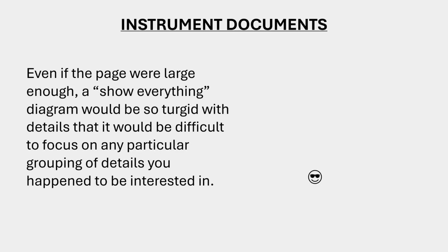To fully understand the control system, technicians often have to switch between these diagrams. You might start with a PFD, the process flow diagram, or a P&ID, the process and instrumentation diagram, to understand the overall process. And then you move to a loop diagram for wiring details, and then you can finally check a functional diagram to understand the control logic. Each one gives you a different level of zoom, just like switching from a satellite map view down to street level. Together they give you a complete picture of the process.